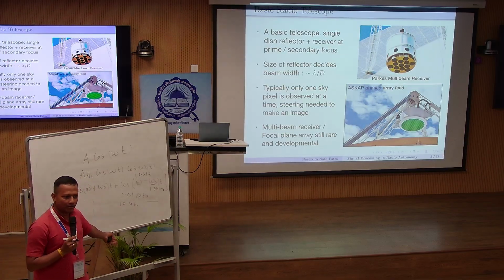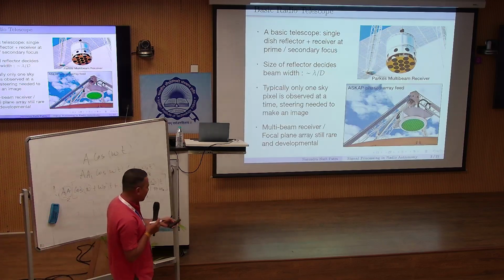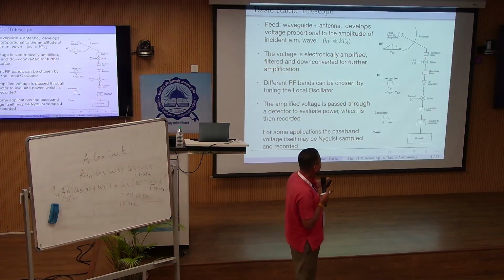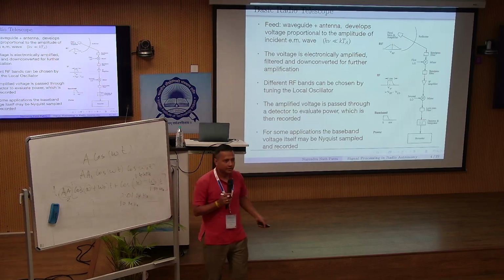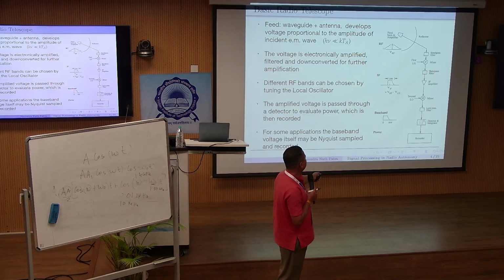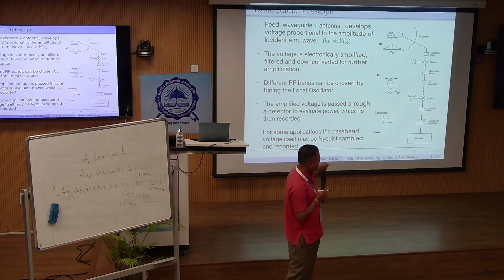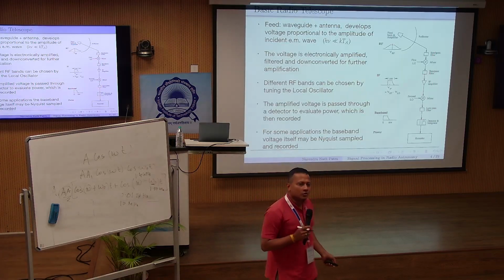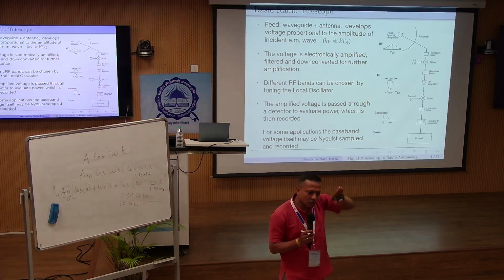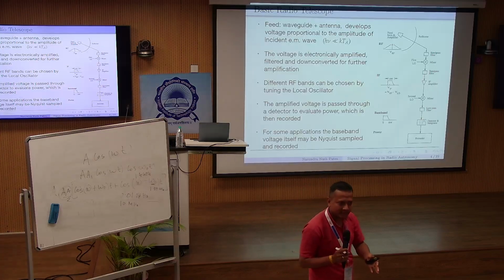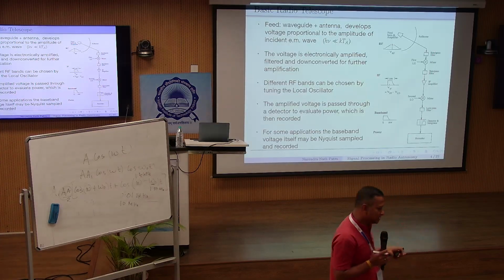Now our processor can actually handle this, right? So that is why you see this mixer sitting there, and this filter, it is basically filtering out that high-pass component, this one, right? And then it comes to another level of amplification. Forget about this part, people used to do it earlier, but now most of them don't do this, okay? So effectively you are mixing the signal to convert that RF frequency to a frequency which you can handle, right? And this process is called heterodyning, okay?